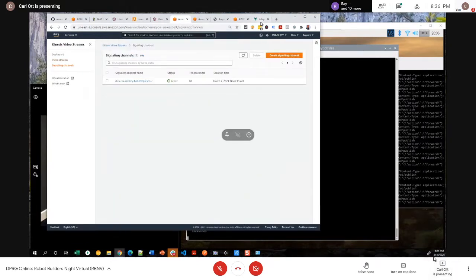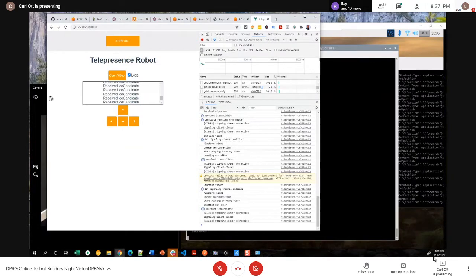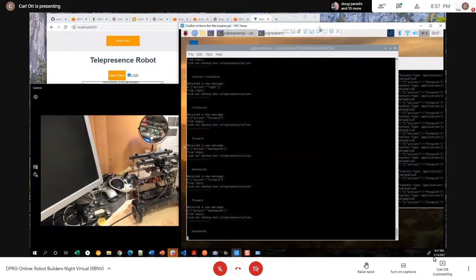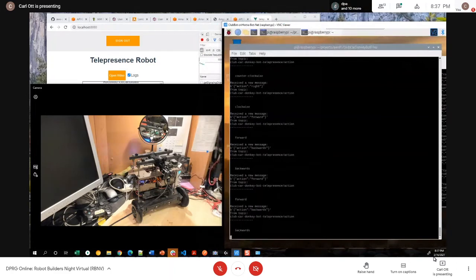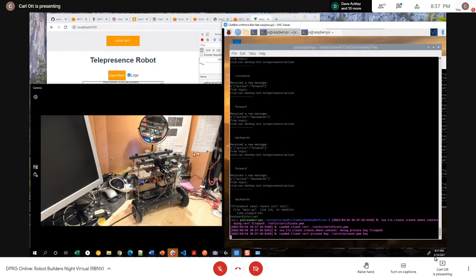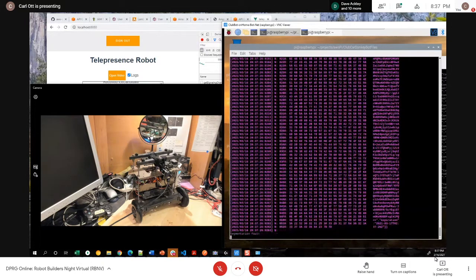So to show that, we'll leave this web page up and running, right? And I'm going to show a couple things at once. First, I have a mirror here, because on the back side of the robot, right about here, I have these little lights that show status, and this one right here is a yellow one. So watch what happens when I halt the client on the Pi. See how that yellow light went out? Oh, and now it actually said segmentation fault. So I think that's the Kinesis thing that has the segmentation fault.